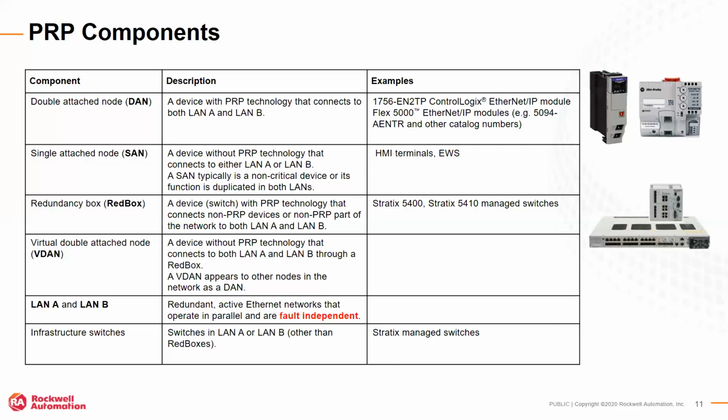The RedBox, in our case, is a Stratix 5400 switch that has the capability of being an interface for PRP directly. That gives us the ability to put devices that don't support redundant or PRP natively onto the PRP network.